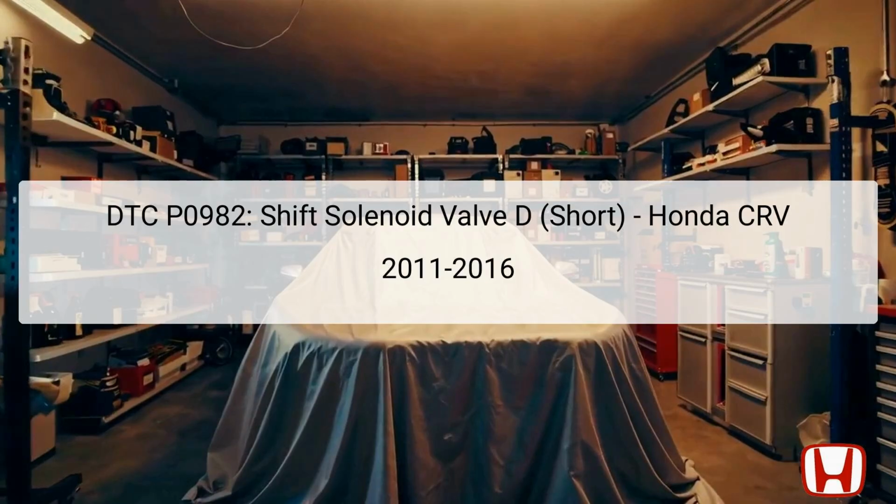When diagnosing this code, technicians should first consider the electrical aspects, including wiring and connections, rather than focusing solely on mechanical components. It's vital to utilize the Honda Diagnostic System, HDS, to ensure that all relevant data is recorded before proceeding with the repair process. Accurate identification of DTCs and their specific symptoms are key to effective troubleshooting.